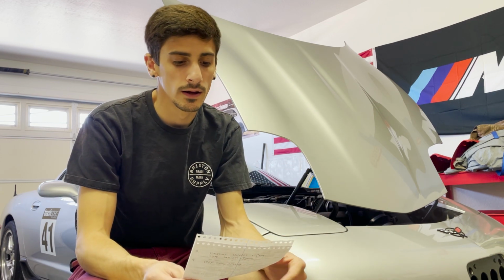You can actually get those on eBay, both the reader and writer, and probably like 20-30 EEPROM chips for like $10. So you actually need a removable chip that goes in the DME, and then that reads it. You cannot directly read and write to those. You have to actually install a different chip each time you want to write a tune.